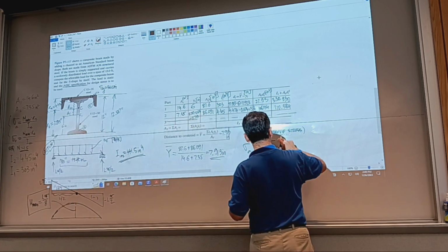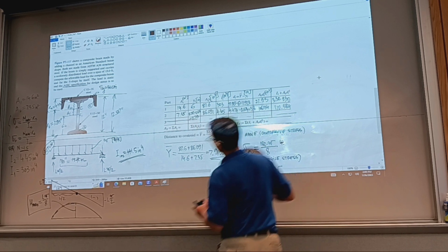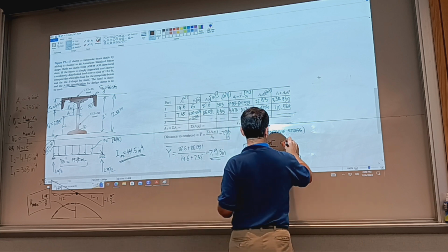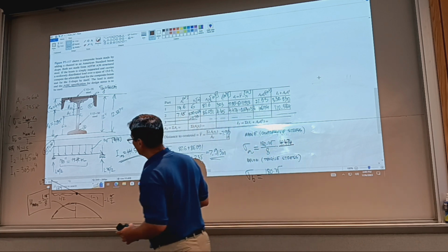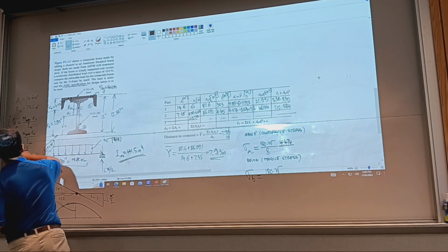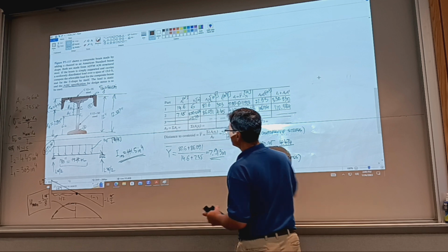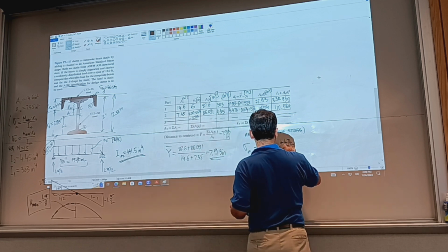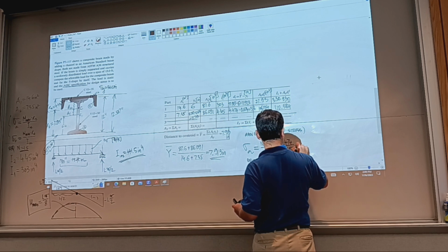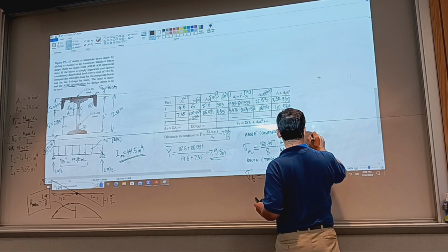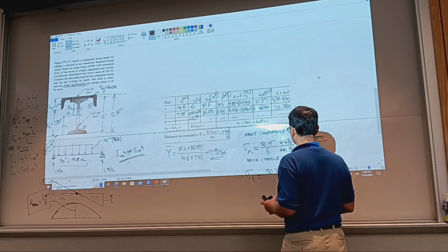So the moment, and then times CA, which is 4.474. This is CA over the area moment of inertia that we calculated, which is 441.5. And this is going to be SY, that is 36,000 PSI over 1.5 design factor.